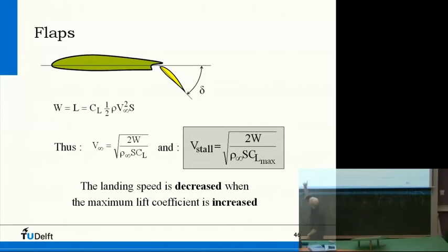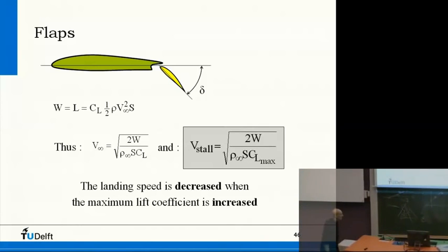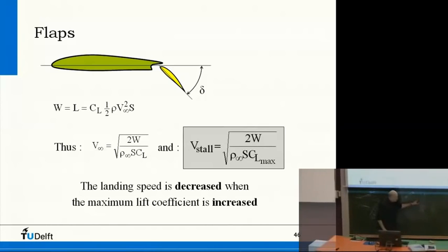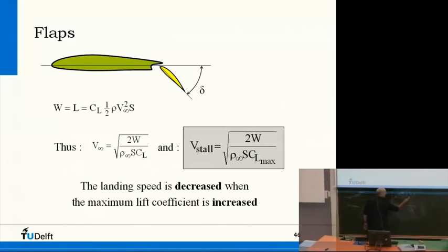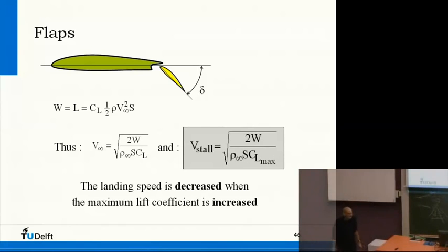Well, from this equation, of course, you can make an equation for the stall velocity, because this is something that you should avoid. No matter what you do here, increasing the angle of attack is not going to happen. The CL stays down, right? So you should not cross this one here. And in the cockpit, you see all kinds of signals when you approach this CL max.